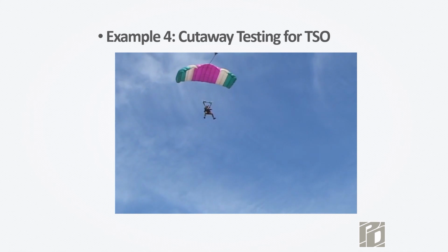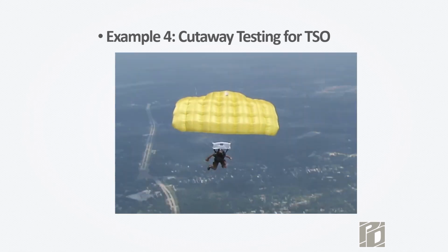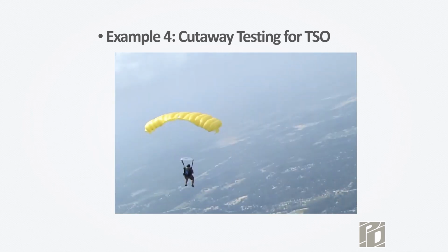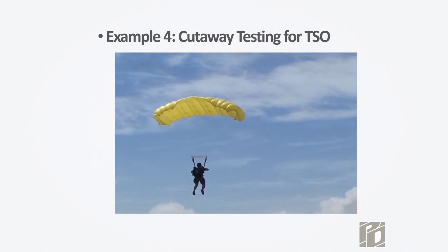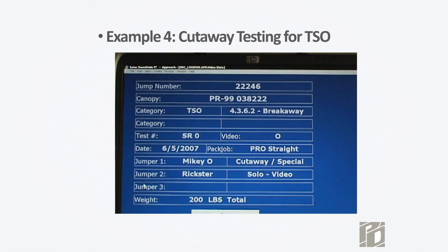So he's hooked up backwards right now, and the test parachute is on his chest. That was a 99 on a simultaneous cutaway and reserve ripcord pull. You've got to be good at flying a parachute backwards, but you don't have to be good at landing it, which is kind of nice. Unless somebody packed a chest mount wrong. It actually looks wrong when you put it in the container because the container is around the front, but the parachute's supposed to face the same way. So when you put it in the chest mount, it looks backwards.